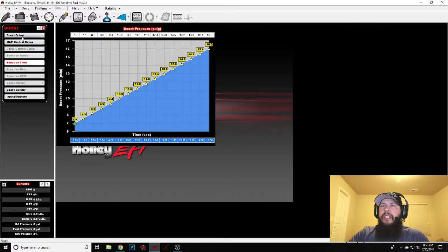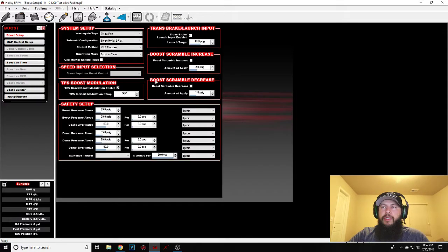So sometimes when you're struggling with the boost control, especially with the target-based stuff, you still have to be cognizant of what the duty cycle is actually doing. So just be aware of that. If you want this 10 psi target to happen quickly, you might have to use an advanced table to retard some timing so that it can get up there quick, so that duty cycle doesn't have to do anything crazy to get it there.